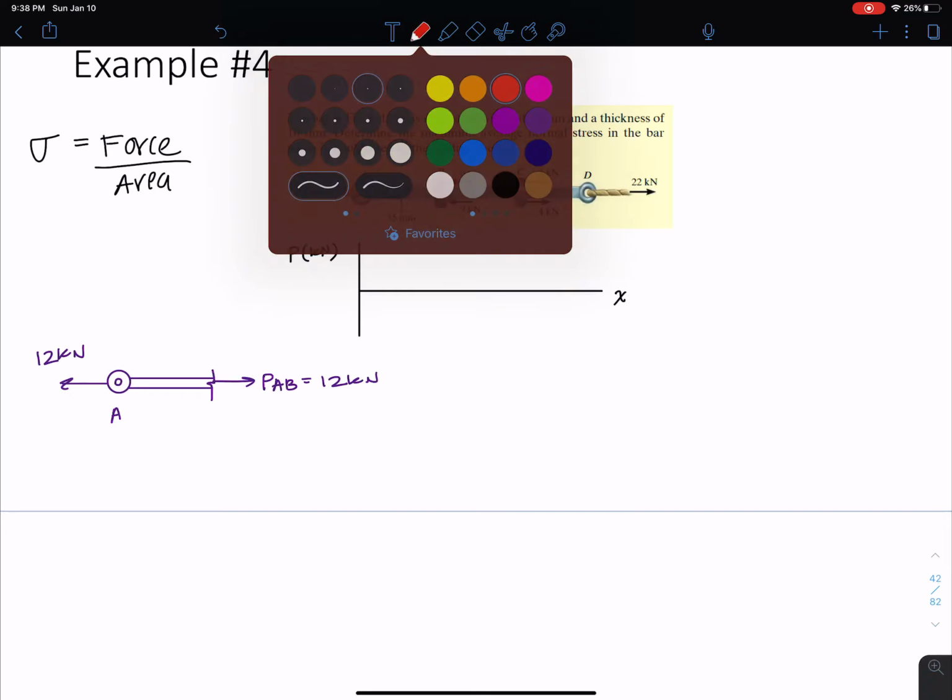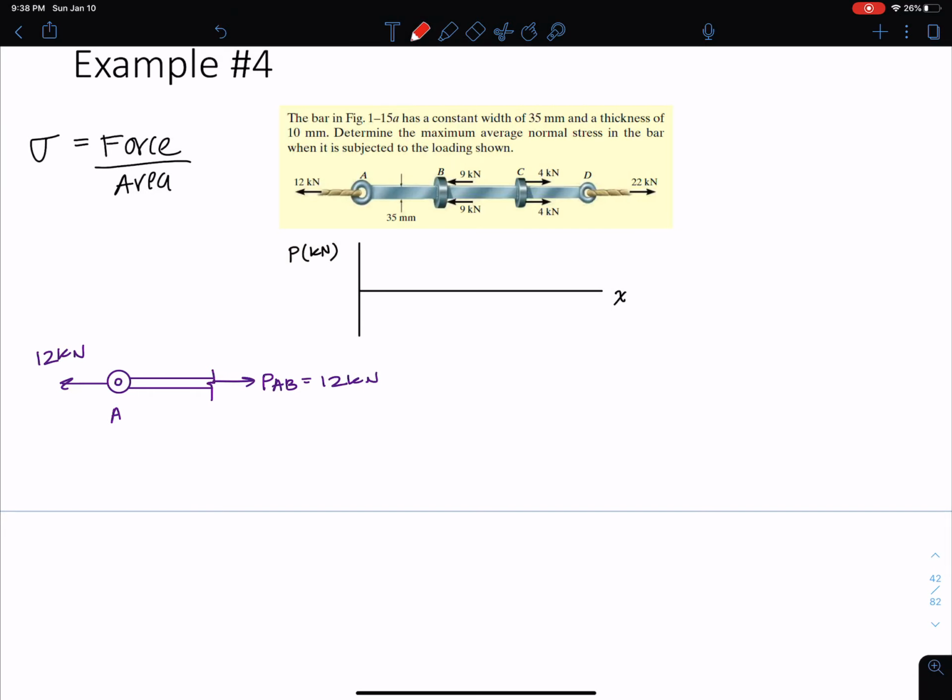Okay, just so we know, I can give you some context here. We also expose a shear and a moment, right? But why do I not care about those right now? Because I haven't loaded the bar in that direction. There's 0. I don't have any shear or moment. I haven't loaded the bar in those directions.